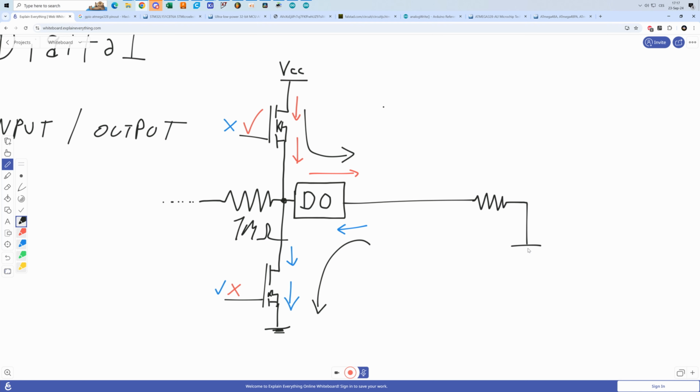So if we connect an LED, sorry, the opposite way, like so, for example, and one LED that will be connected this way to the positive supply rail. If the circuit is logic low, what will happen is that this LED will light up, this one, because the current will flow from the supply rail through the resistor to the transistor over here.